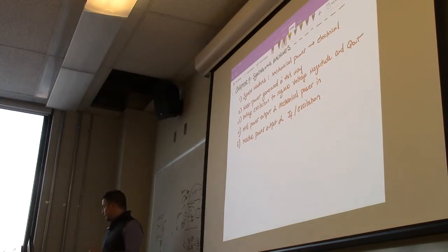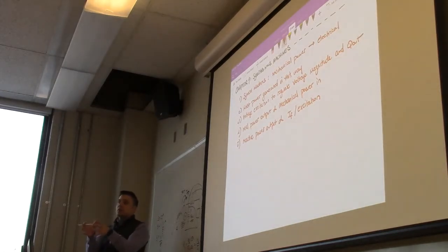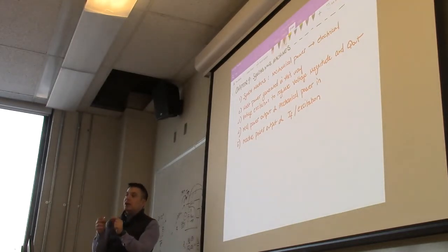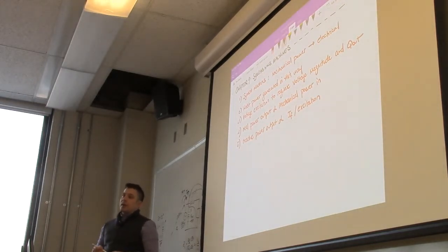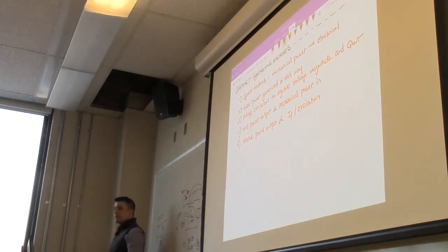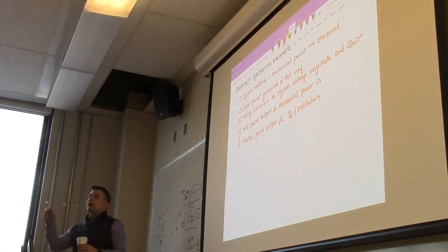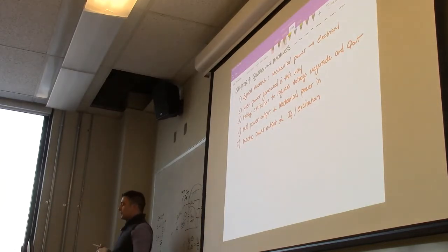Sorry, what's I sub F? I sub F is something we haven't introduced yet. That's the reason why I was looking at this and kind of deciding what I wanted to say. So you have the stator of the generator, you have the rotor of the generator, the part that turns, and the wire inside of the rotor is called the field winding. So to control excitation, you essentially control the amount of current flowing on that field winding. And that's divided by or slash? That's just slash, meaning the field winding is synonymous with excitation.